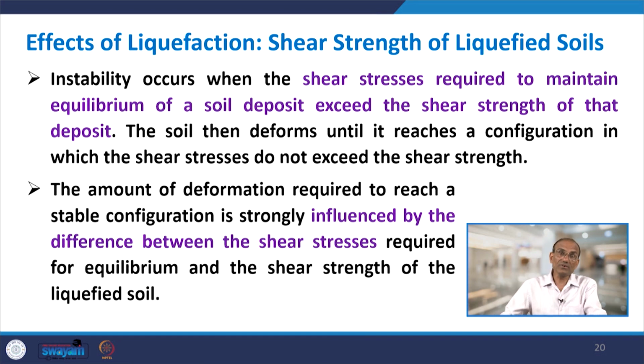The amount of deformation which is required to reach a stable configuration is strongly influenced by the difference between the shear stresses required for equilibrium and the shear strength of the liquefied soils. So, on one side you have shear stresses, on the other side you have the shear strength of the liquefied soils. Whatever the difference is, that will be manifest there.